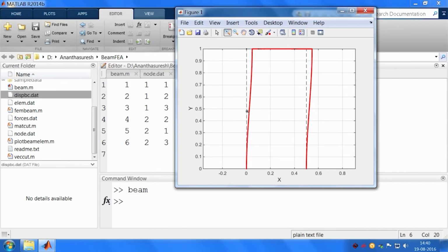One more thing before we go to nonlinear code that you need to notice is that from here to here I have a single beam element. So, in finite element analysis the unknowns are only the degrees of freedom at the nodes. So, I know the xy displacement and rotation at this point, I know xy displacement rotation at that point, right. So, if I join this point to that point after displacing them according to their values that I compute using finite element code, I would have a straight line from here to there, whereas here we have a curved line like this.